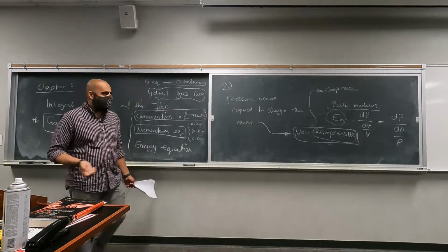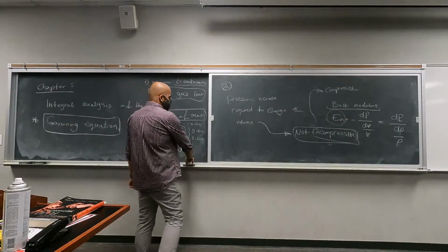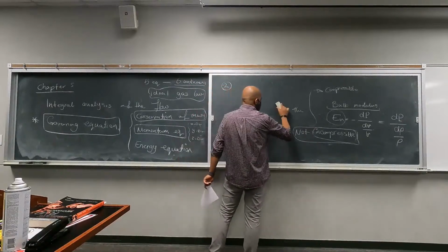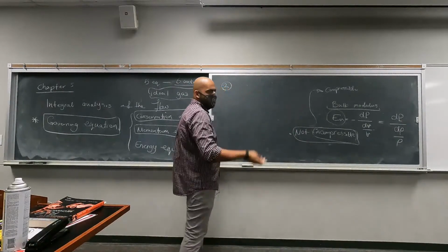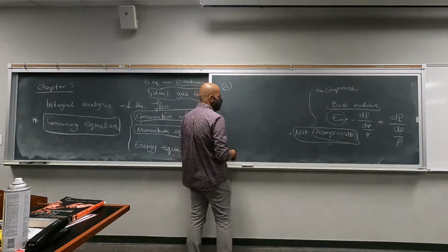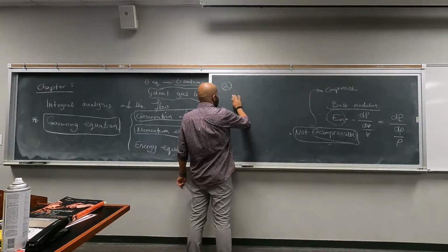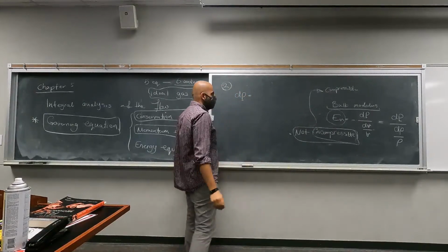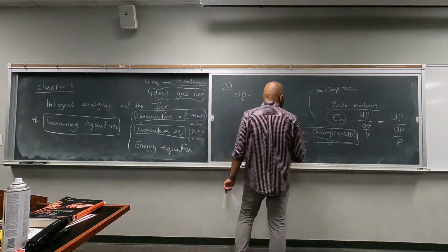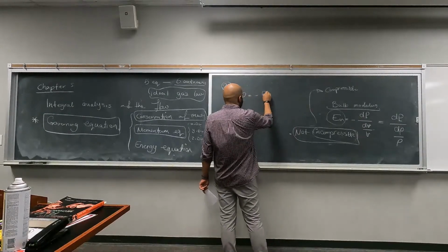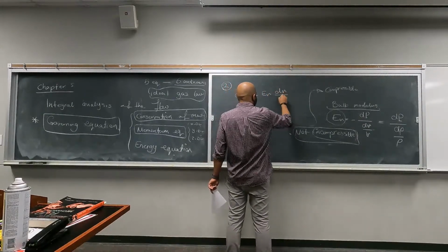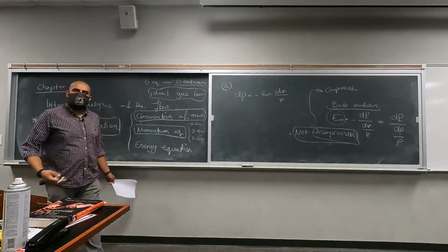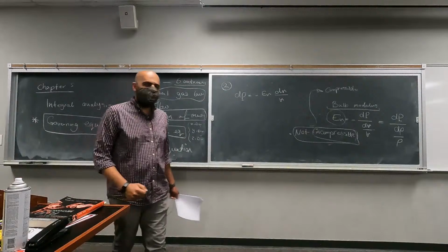We actually have the value of the seawater bulk modulus in the book, but you didn't need to have the value, and the value wasn't given to you. You could just assume that this is constant, okay? Just a constant value, just a number, whatever, 1 million, whatever. So we want to find the change in pressure. So let's rearrange this equation for pressure. dP is going to be equal to negative E_V dV divided by V, right? So that's the equation we want to use in this problem.